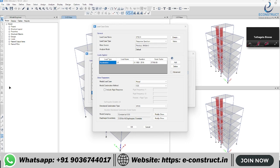But if certain few columns are non-orthogonal, then the problem comes actually, because those columns would be getting very heavy. Let's say for an example, there is a column which is orthogonal, and just next to that column there is a column which is non-orthogonal. Hell and heaven difference would come between these two columns in terms of reinforcement. So that is very difficult to execute at site also.